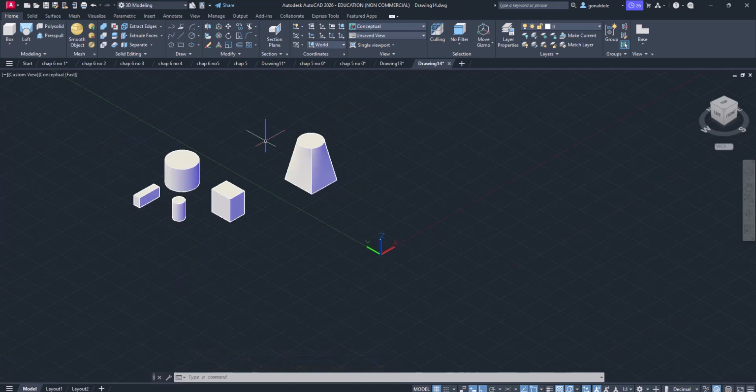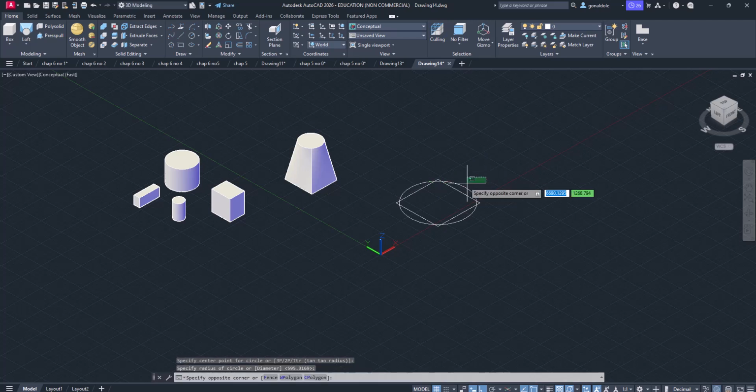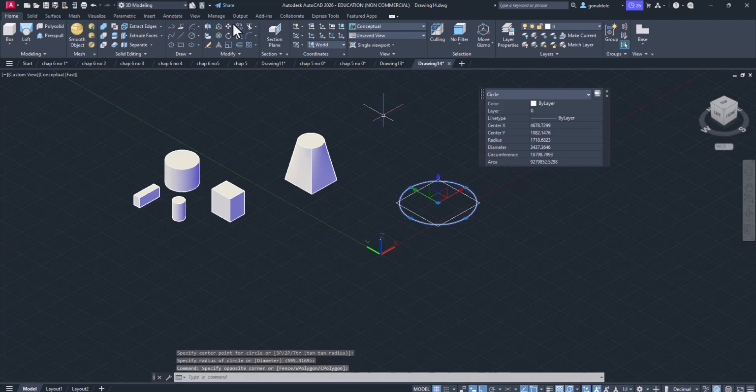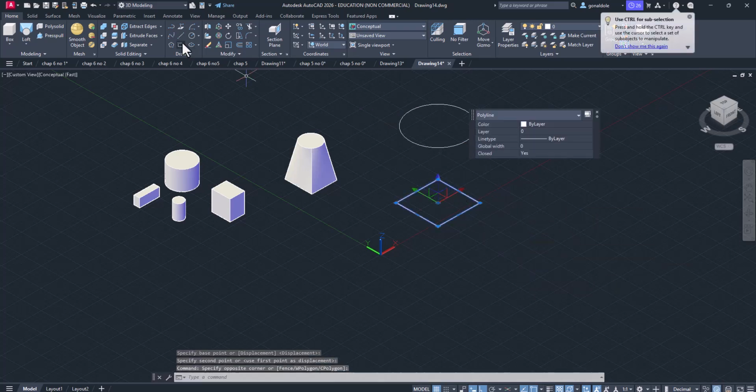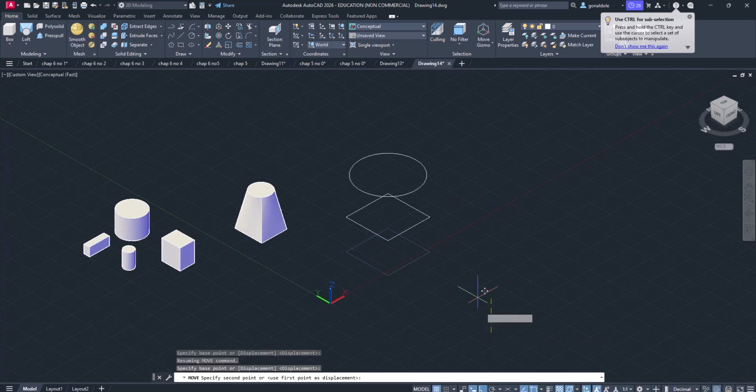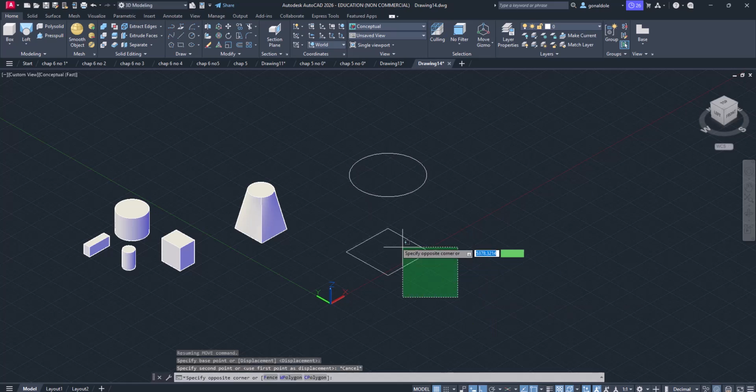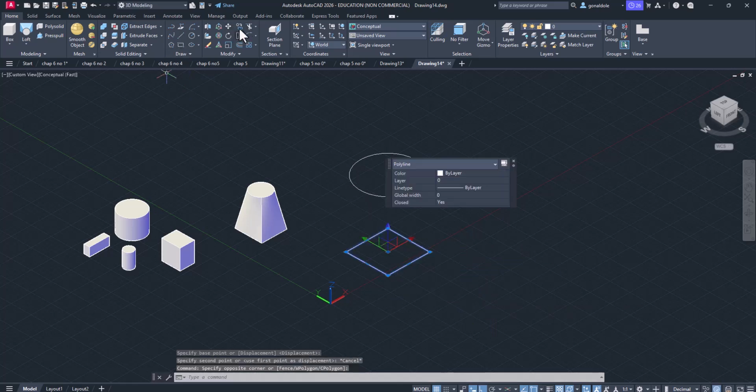But the beautiful thing about the loft is you can use more than two geometries. Let's try it again one more time. I can have a square here, and a circle in between just like before, and now I'm moving the circle up. Then let's assume I have a square on top again. So let's move the square up. Oh, sorry, now it's going to be copy because I don't want the square down to disappear.